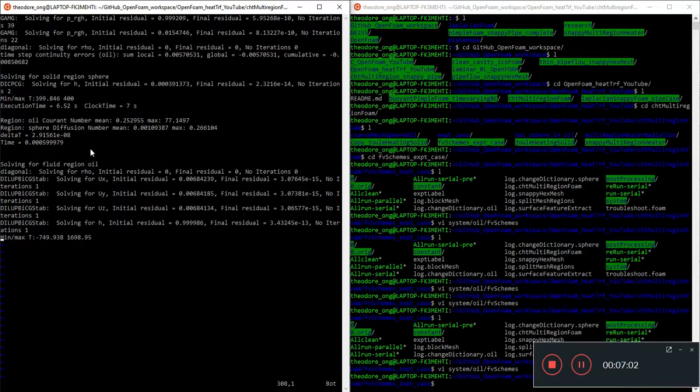Now my first gut instinct was, was this because the solver could not resolve turbulence? So I reduced the temperature to 400 Kelvin instead of 500 Kelvin, where the Rayleigh number is such that you will not be in the turbulent regime. How do I know that?